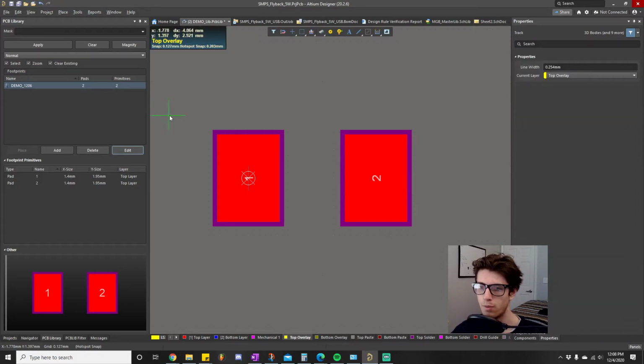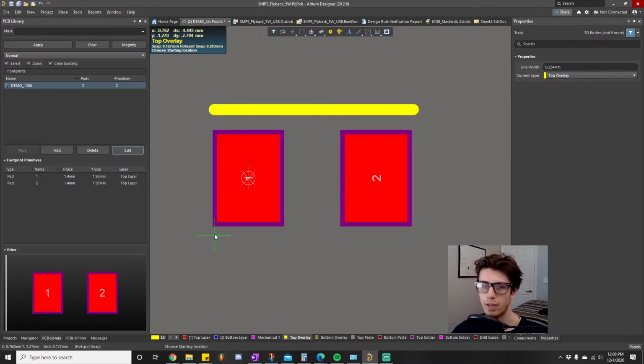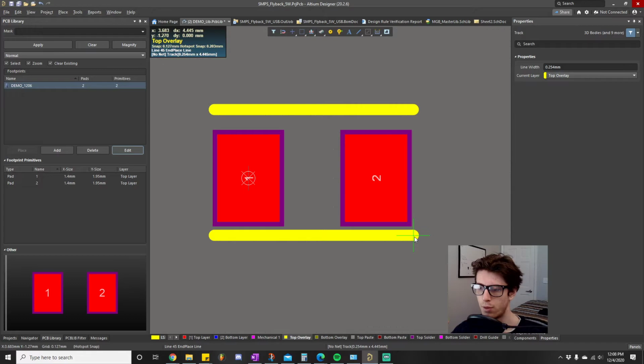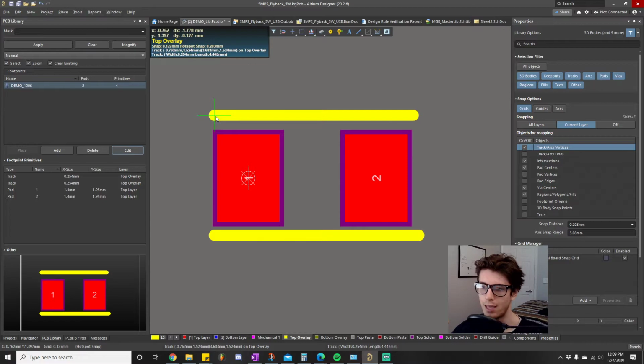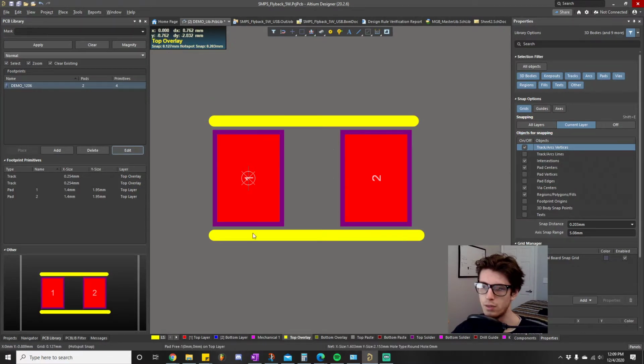This will really help when you get your board manufactured. Whenever you see these, it helps you spot them easily, and it helps you in person when you're looking at the board, like a visor, so you can match things up, because you'll have hundreds of these little teeny components, and these are small, right? We're talking millimeters here. So when you see them, it helps filter the chaos a little bit, so you can more easily spot your pads.